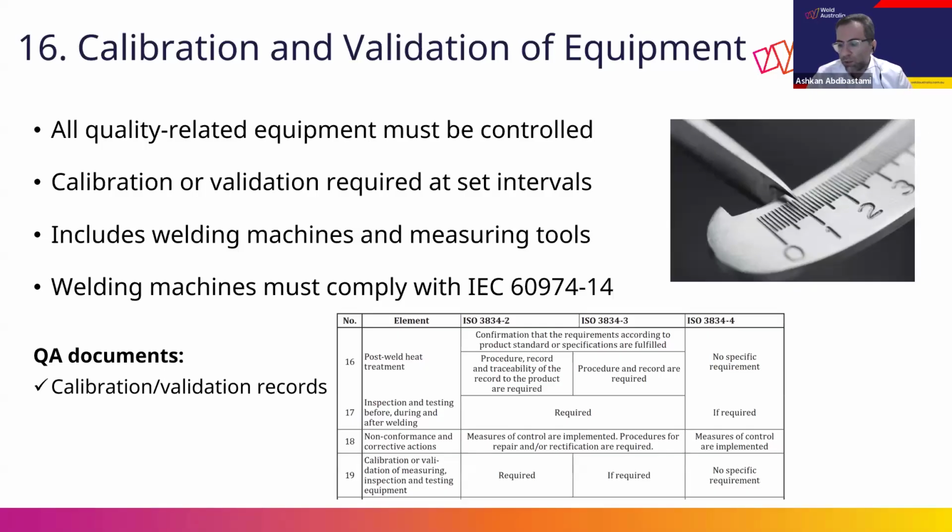You need to have a look at your welding standard and what standard you are complying with. If that standard permits and allows you to use that WPS with that range of qualification, you can use that for the repair welding. Yeah. Thank you.